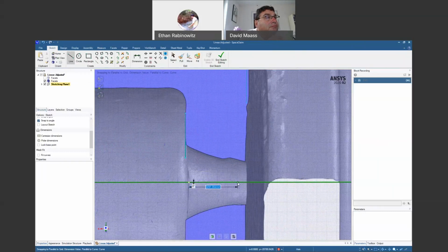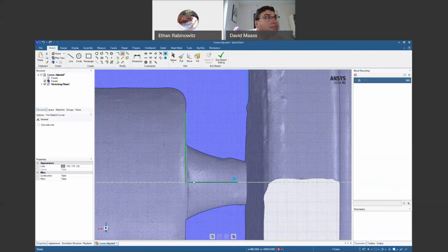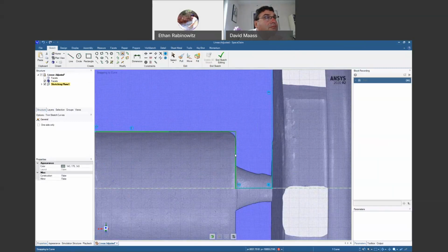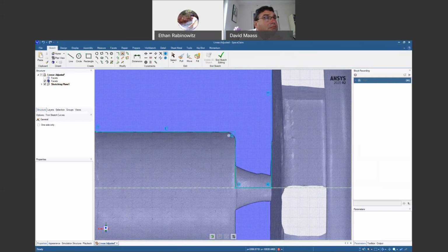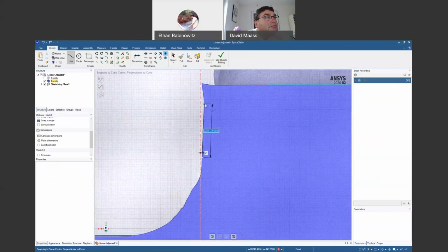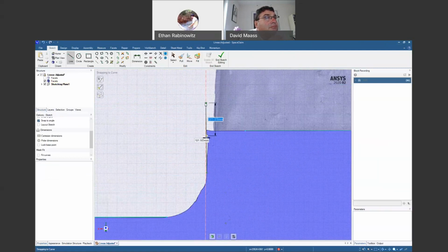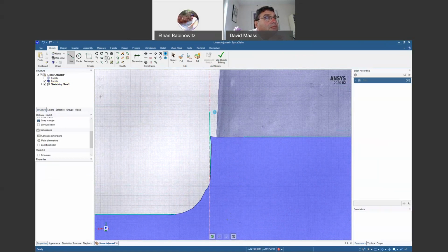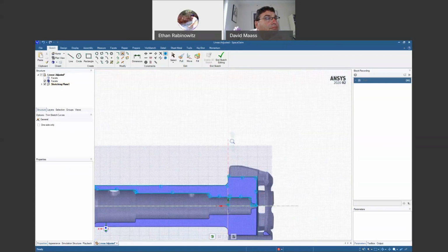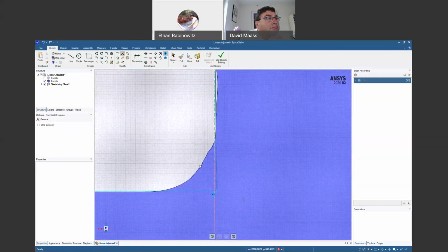And I'm just going to sketch a line across here. And then we'll create some corners like there to there, here to here, here to here. I've got one line to create up here. Again, if I think things should be at a certain angle, I could always sketch it like that, but it seems like, based on the design and the intent of this, that they're probably not at those angles. Right. So we'll trim that, make a corner here. All right, so I think we have a complete profile, and while I'm here, the rounds we can either add at the sketch level or add at the 3D level.